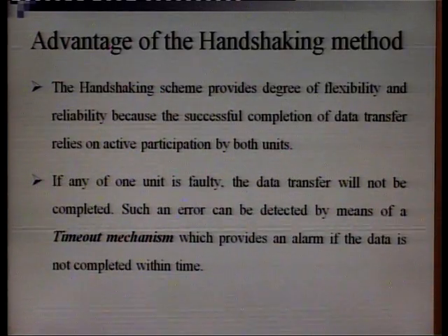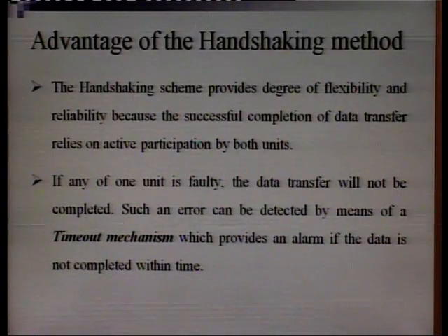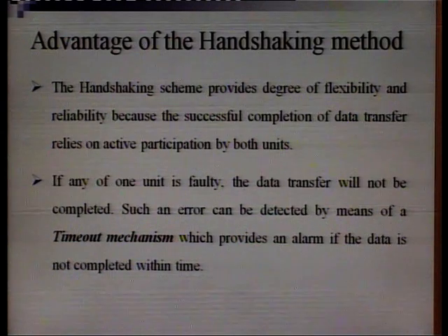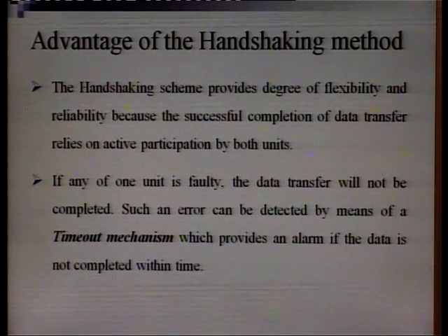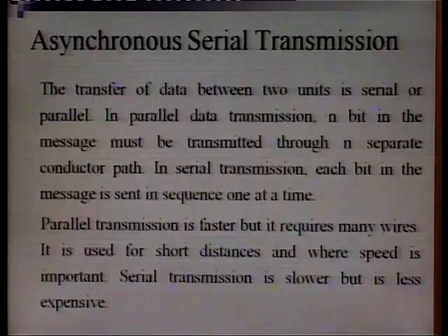Such an error can be detected by means of timeout mechanisms, which provide an alarm if the data transfer is not completed within the time. The timeout mechanism is managed by the internal clock of the computer system, which gives the alarm if the particular data is not received within the particular time. So these are the advantages of the handshaking method.